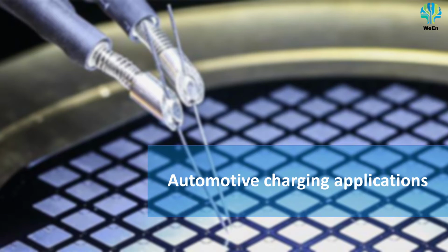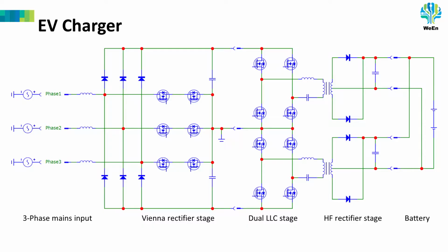First, we look at automotive charging applications. On this slide, we see a simplified schematic overview of a stationary EV charger. It is a three-phase application, and we see a Vienna rectifier stage that combines the input rectification with power factor correction. In the middle, we see the connection to the mains neutral. So this Vienna rectifier stage delivers both positive and negative DC voltage.